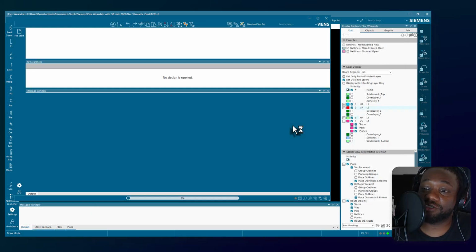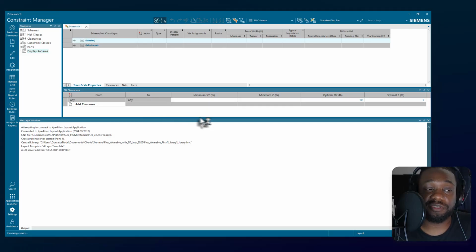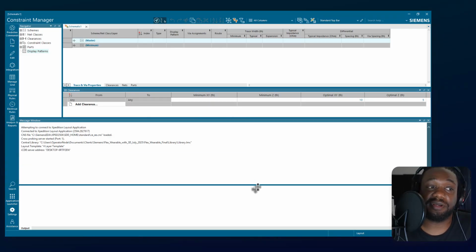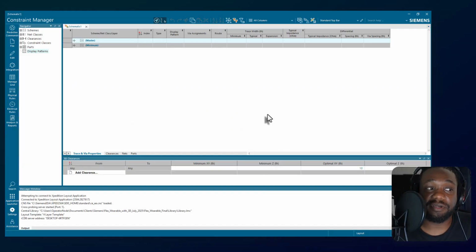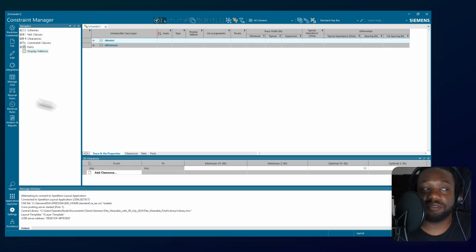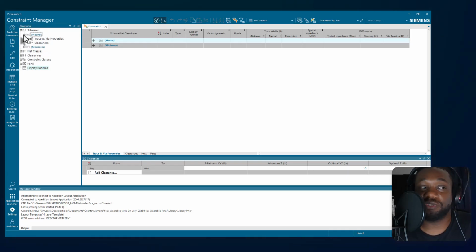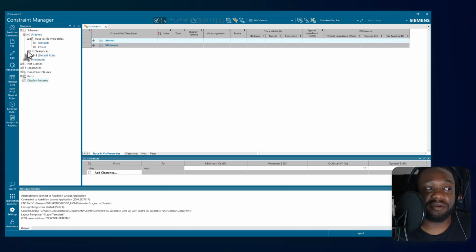The constraint manager is the biggest thing that I use to evaluate a PCB design software. A PCB design ECAD software is only as good as its constraint manager, in my opinion, because the constraint manager enforces the rules, well, the rules we need to meet our requirements. And if we don't meet our requirements for the product, we have to redo the board anyway. So the constraint manager is the most important thing. It's like the referee for the game, or the rules of the game, right? If you don't play by the rules, you're not gonna win the game.